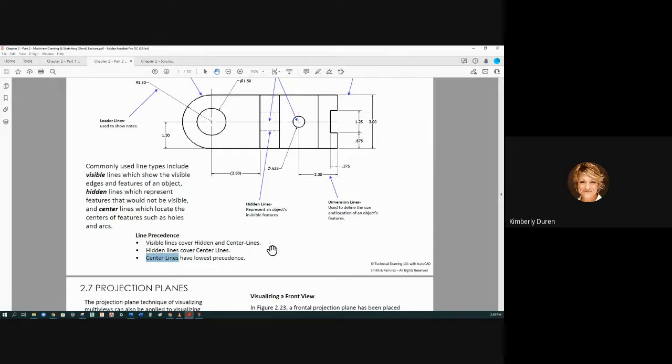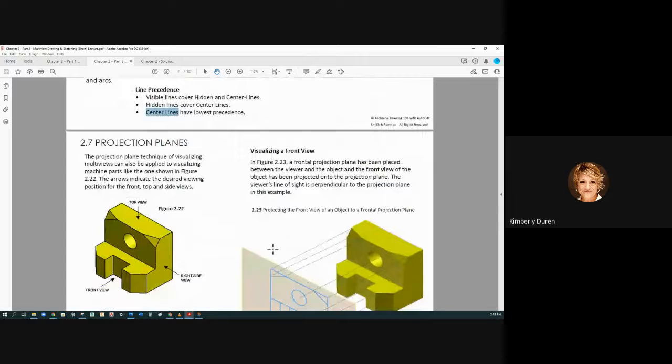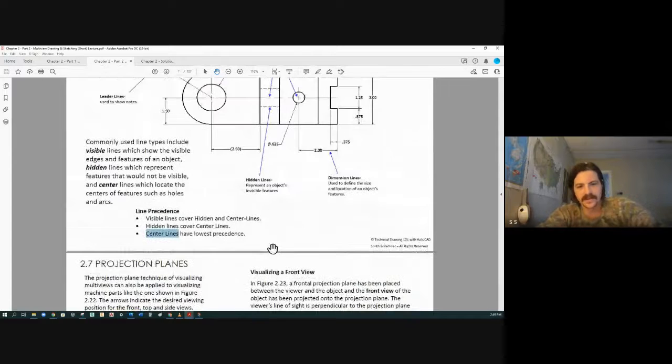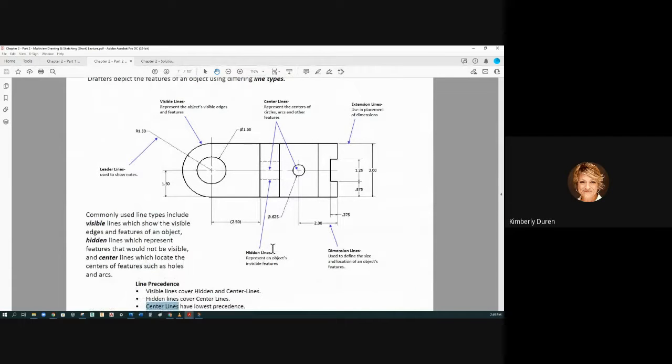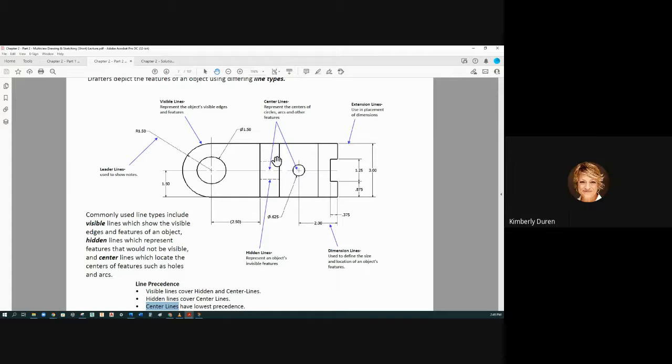And then I put my center lines in. So talking about, yes, you have a question? So when you go in and make the visible lines, do you put the hidden lines in afterwards to straighten it up? No, you put these hidden lines in because you wouldn't know that this wasn't solid all the way down. Right? Okay. This just tells you that there's something inside here, so you better go look at another view to see what it is. Okay. Does that make sense?